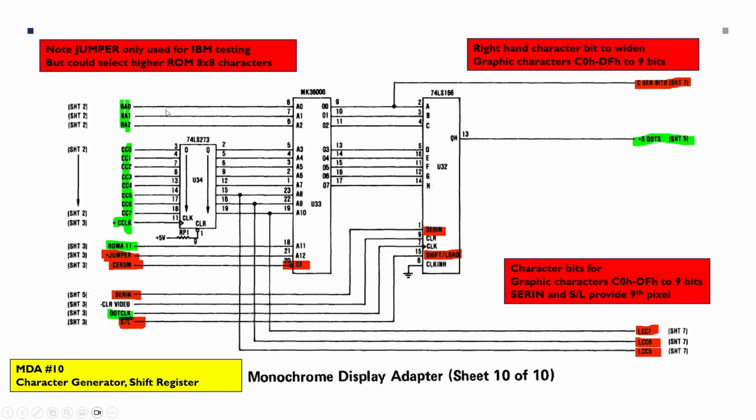So basically what comes out of here, there's a latch from the character video RAM that drives the upper address bits for the EPROM, and then the CRTC row address 0 to 2 drives some of it. There's a bit of complexity here as well, in that this is actually the row address 3 but goes through some multiplexer. And again, I would say that we can probably simplify this quite a bit by wiring this one down into here. So we're going to change this around a little bit. The reason for this, I think this ROM was also used for the CGA cards as well, and there was a complication that isn't required here.